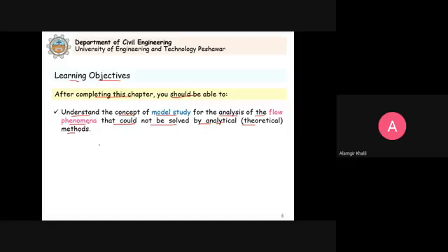Now we studied earlier, even in fluid mechanics too, that, for example, we applied mathematics to solve fluid flow problems. Then in hydrodynamics, as this area was called, the fluid was treated as ideal. When you treat the fluid as ideal, it means that it has no viscosity.